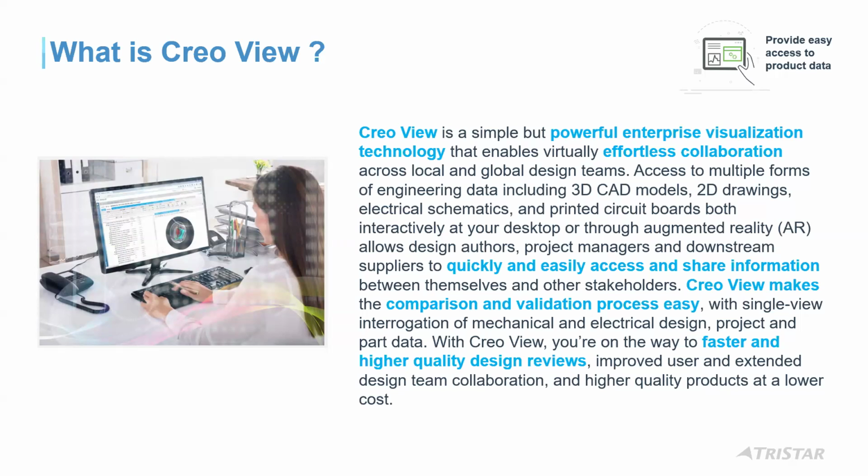You can do a lot more with different levels. With the Express viewer, you can pretty much view information and interrogate it. With some of the other viewer functions on the Lite and the MCAD versions, you can do a lot more. You can actually build assemblies by bringing parts together from scratch. You can start animating things and so on.